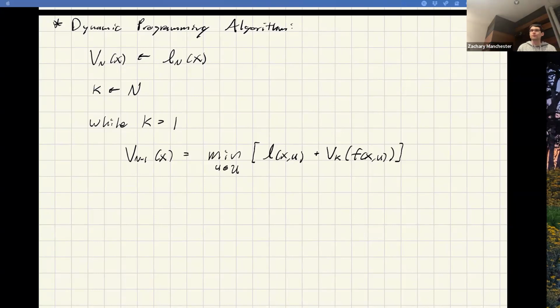And the idea is if I go backwards, that second term with the cost to go function, with the dynamics plugged in, includes the optimal cost for the whole rest of the problem, for the whole future. And by computing that again, I can back up one step at a time and recursively compute that until I get to the beginning of time, as far as I'm concerned. And now I have the cost for the whole problem in there. And that encodes the whole answer.